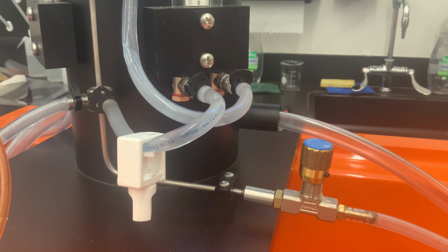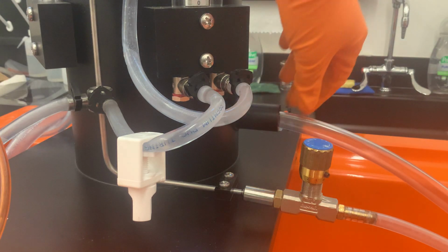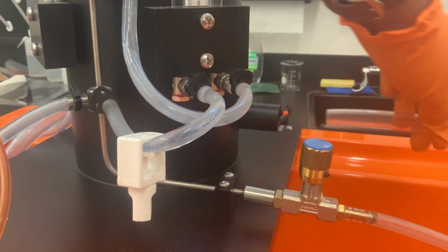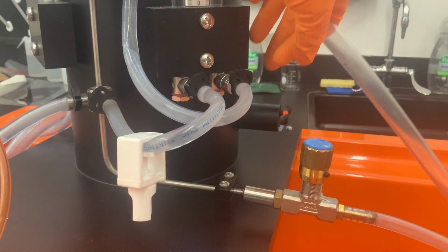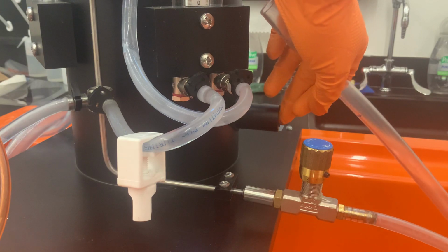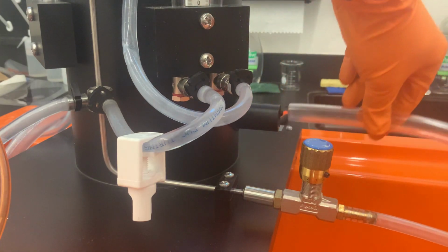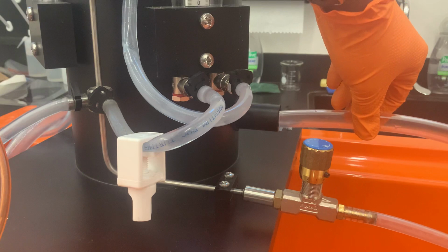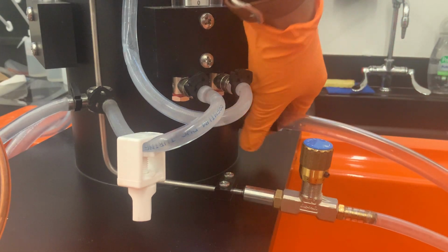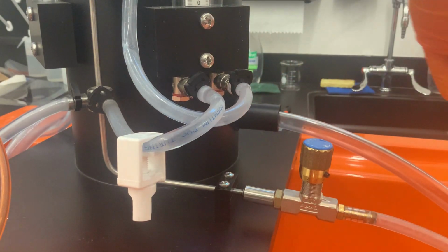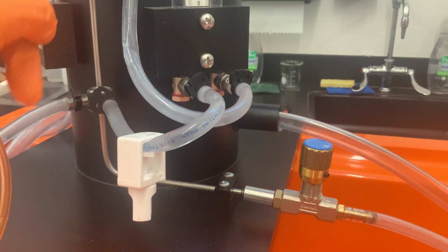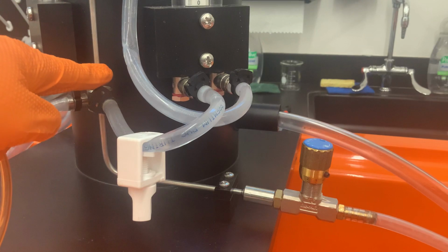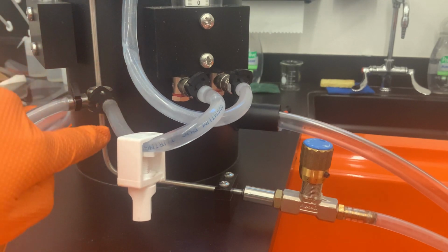This is the bottom section of the system here. This is the overflow from the constant head tank. Whatever water doesn't go through the pipe, the excess water will go out through this port. We put a pipe so that the water doesn't fall on the system. It just falls away from the system. But this here, this is the pipe, if you remember. This is the pipe we're testing to measure head loss.